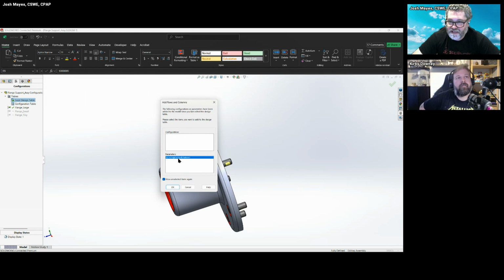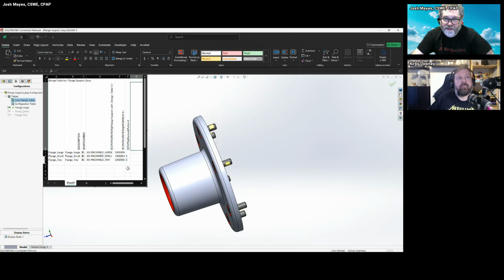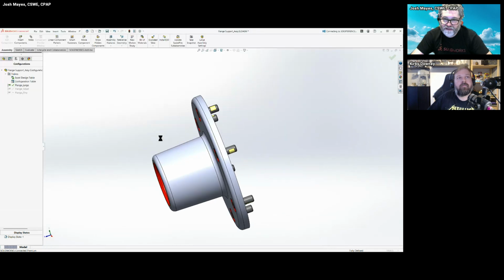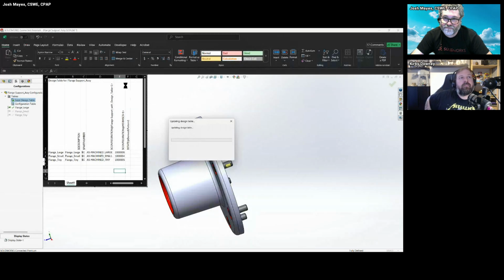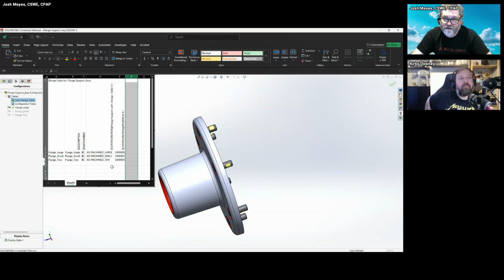Interesting. Okay, so the state of my derived pattern shows up in this list. That tells me that I have a variance between my configurations, probably because I deleted it and re-added it. And by default, my other 2 configurations did not have that turned on. I do want that turned on. So I'm simply going to unsuppress them using the design table, go back in and delete that row because it's really not something I want to ever suppress. I do want those always included.